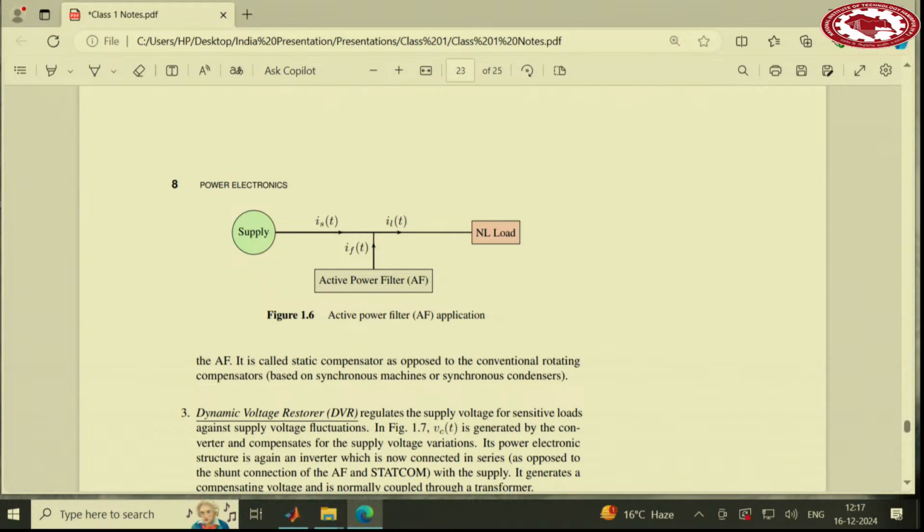For that reason, the power grid does not like that current, because distortions or harmonics have multiple impacts on the power grid. So especially if the load is large, like industrial loads, there are codes and standards by the power grid that would not allow that to happen.